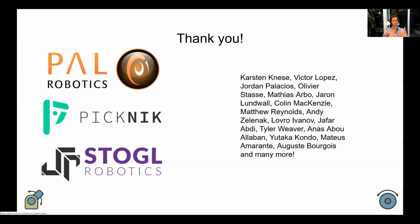But probably the simplest thing, if you want to switch for example to ROS2, would be to write a hardware interface which creates these simple messages first, and you send the same simple messages to your hardware. This may not be the most optimal solution, but as a first step I think it would be the easiest for you, because you don't have to change anything on the robot side. If I understand the architecture correctly. If you have more information, also ping us on the issue list, so we can maybe help you more.